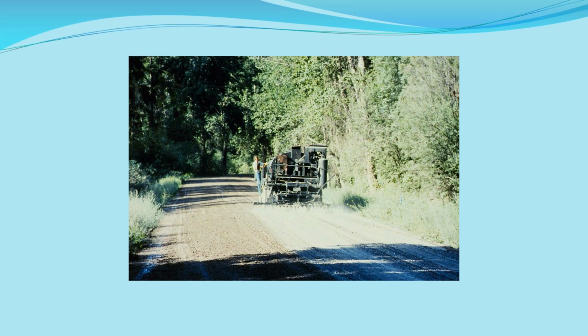In this application, we had compacted that roadway somewhat. We left it a little bit open so we could spray it, shooting about a quarter of a gallon per square yard of the magnesium chloride, and would not allow that mag chloride to run off the road into the ditch. We kept it pretty much in the roadway.